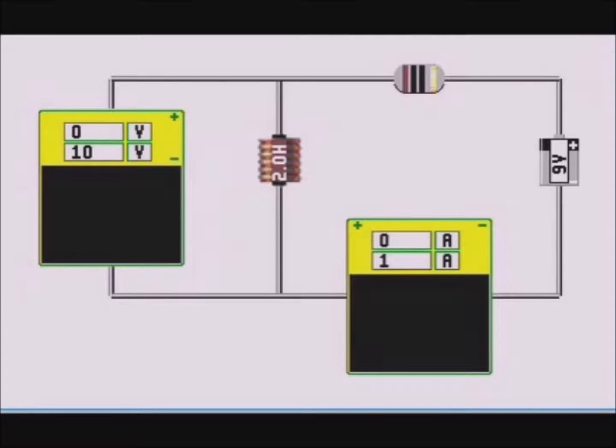An inductor is essentially a coil which may be wrapped around an iron rod. We know that when a current is passed through a coil, a magnetic field is set up around it. This field imparts a voltage, opposing the voltage driving the current. The size of the opposing voltage is dependent on the rate of change of the current. In this example, the current would be 0.9 amps, but this rapid change from zero in the current causes a big change in the opposing voltage.